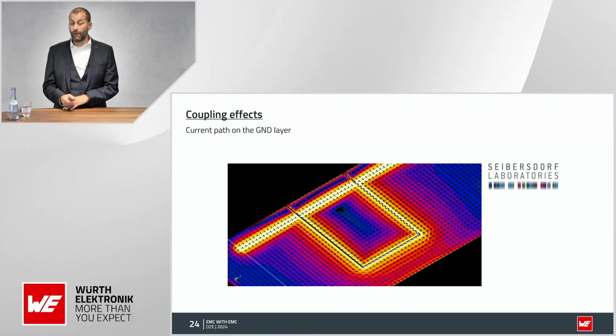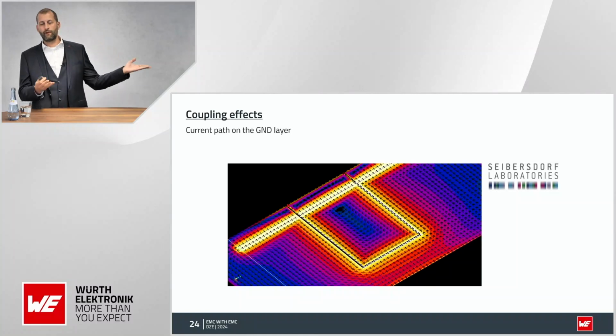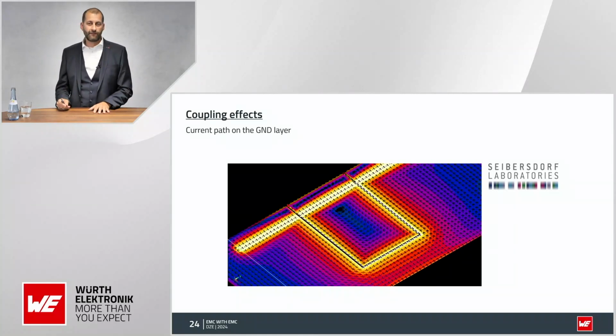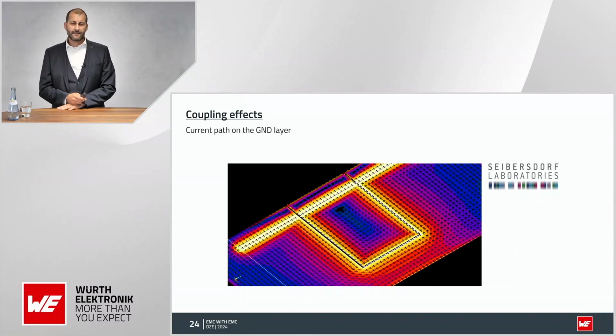What happened? Well, at first we thought, yeah, easy explanation, capacitive coupling. And then we realized, well, the signal is a 1 megahertz square wave, and in that frequency range, you would need a massive capacitance to have capacitive coupling. So what happens is you have eddy current, eddy current inducing a flow in the other direction.